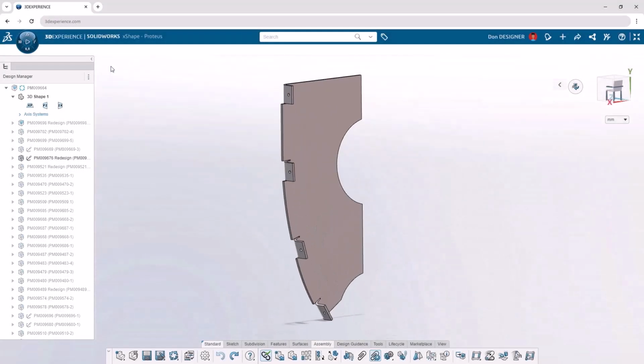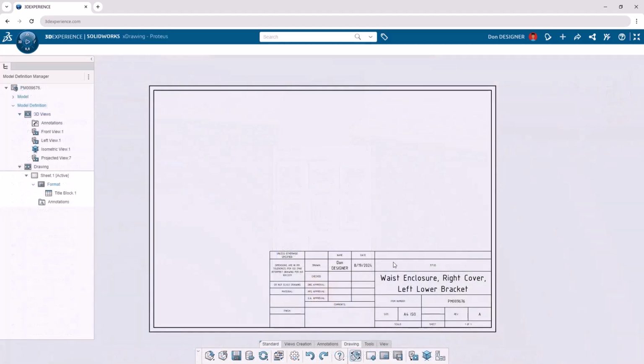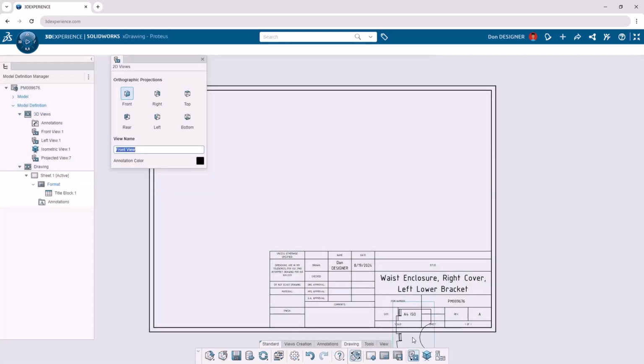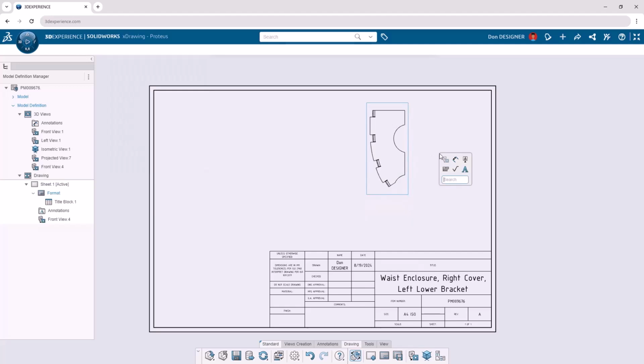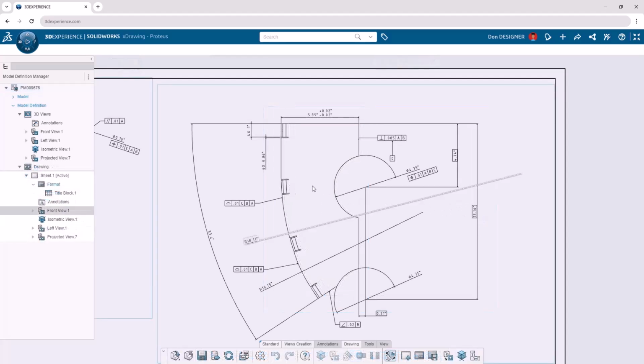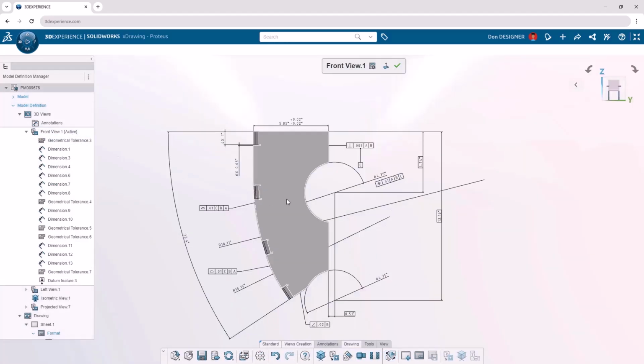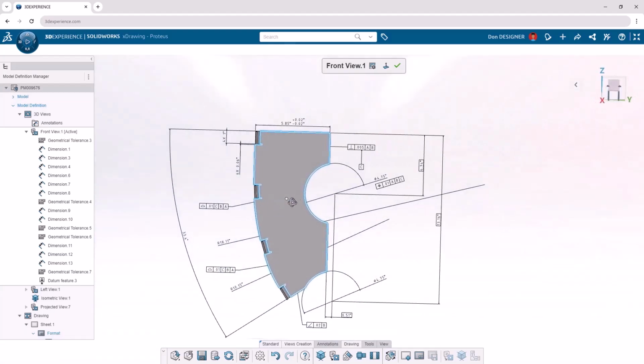This year, we're highlighting drawing capabilities in our cloud tool X-Drawing. It's integrated with the other X apps so you can access it with the shortcut key X. Start creating views in 2D or 3D and annotate all your product manufacturing information to standard. All callouts contain auto-generated annotations, measurements can be adjusted from any activated view, and annotations can refer to multiple model entities and faces. Also, any views and annotations created in the drawing environment are automatically captured in 3D to accommodate for model-based definition.